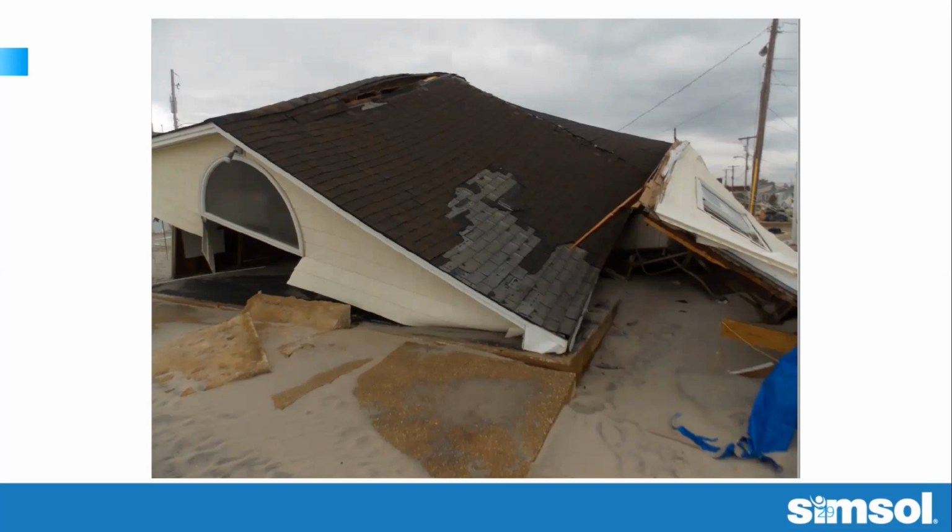And the shingles here that are missing, the building collapsed during the flood event, and subsequent wave run-up tore the shingles off of the roof. That had nothing to do with wind. Because look at the top of the building near the ridge at the upper left of the picture. Notice those shingles are intact. Even the ridge vent itself is intact. So we don't have any wind damage. This is just the battering of the debris, like we talked about earlier.